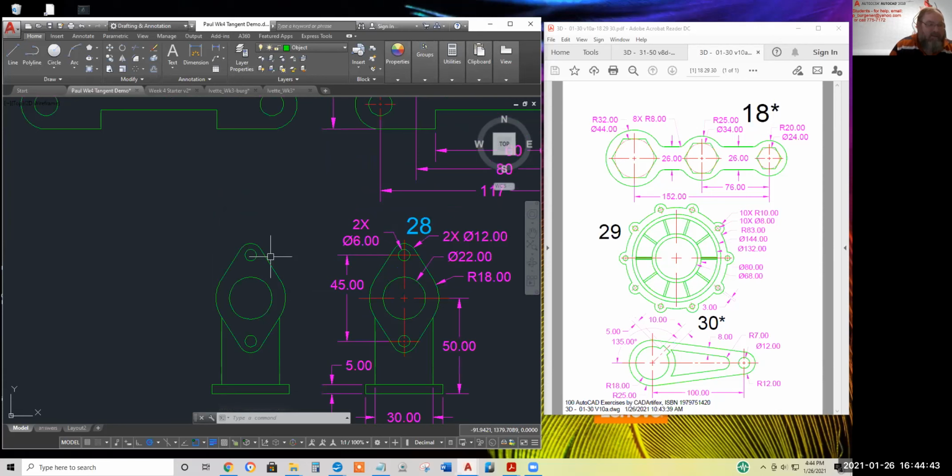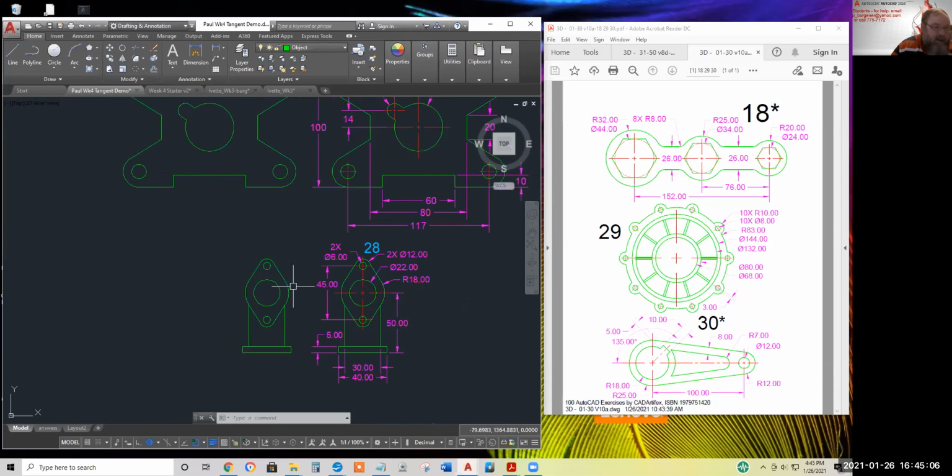You know, a couple students, instead of going tangent, tangent, they put a fillet between the circles. And I might not have noticed if you used for the fillet radius something like 999 units. So the circle, it'll almost be a straight line because the circle is so big.